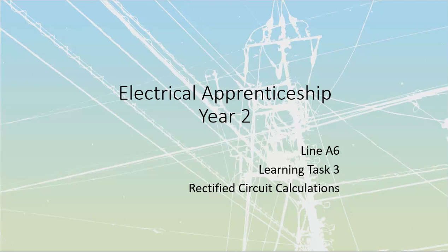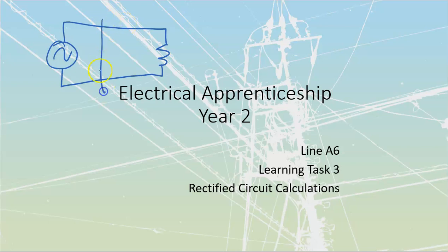But ultimately, what is happening is we're going to take AC that we normally have. We're normally going to have a load connected across our AC like that. And now what we are going to do is put in a block over here that is going to become a rectifier. What a rectifier is going to do is take this AC sine wave that we had on this side, and then create a rectified DC on the other side over here. Okay, we're not showing the guts, it's all the diodes, so we just took a look at that.